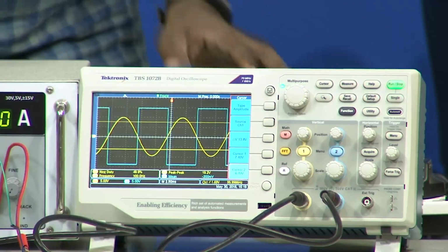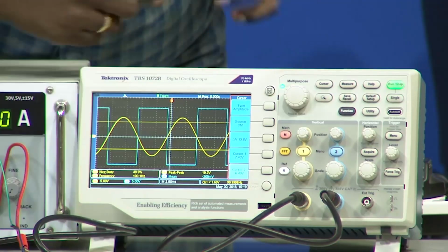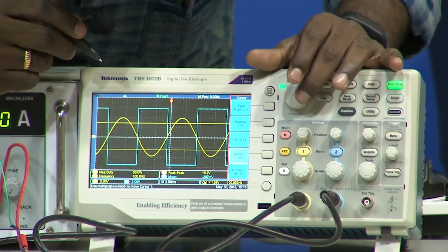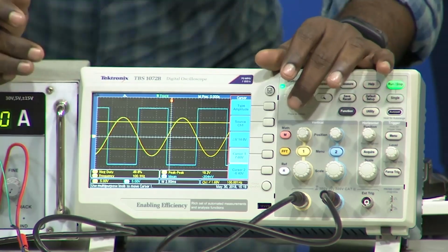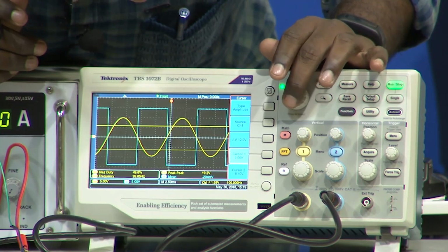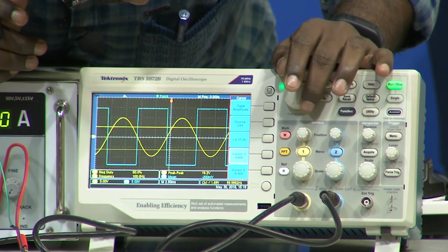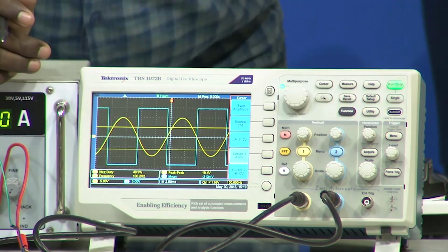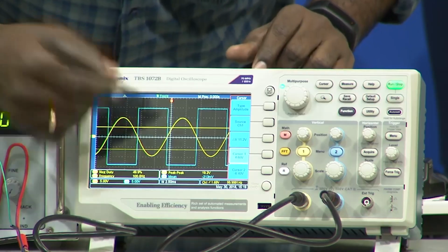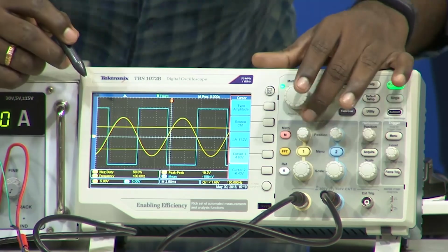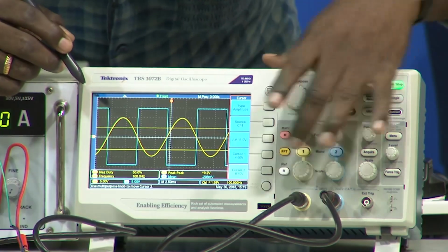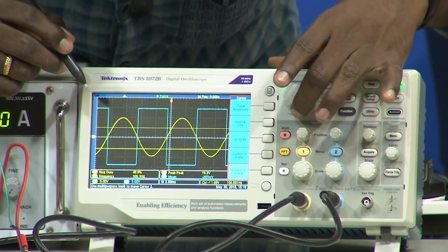we can see here that now we have to replace our cursor points. We will go to cursor 1, we will make it 4.68. Right now it is at 6, 5.2, so 4.8. So cursor 1, this yellow line, is at 4.8. We need 4.6, right? So I will move it to 4.6. Then I will go to cursor 2, I will change it to minus 4.6.